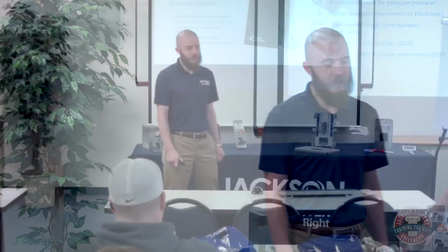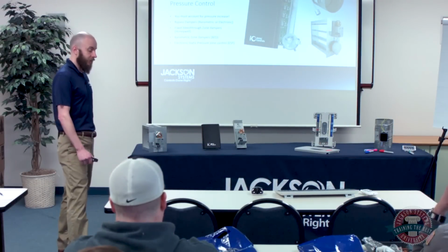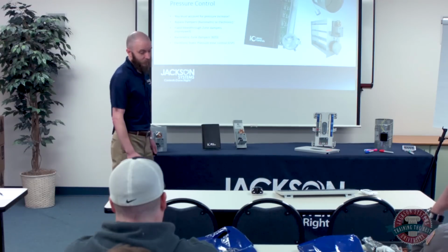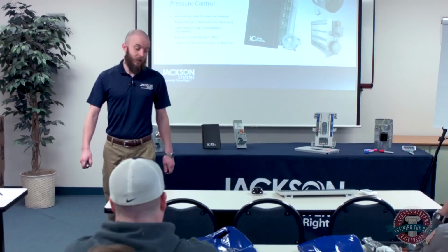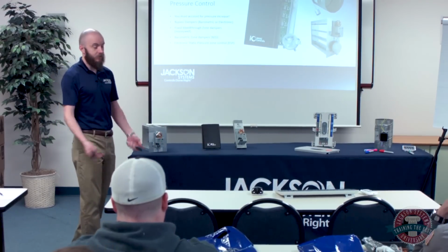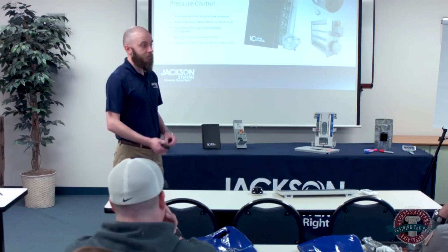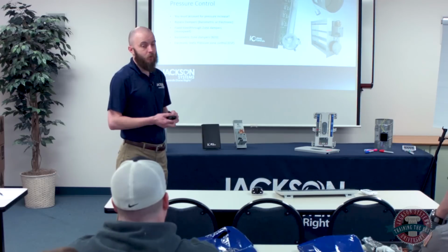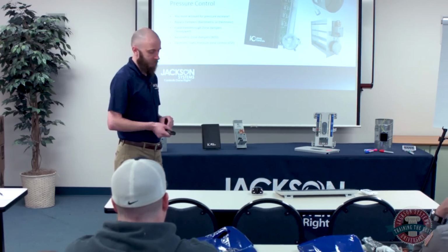We know there's a lot of people out there that install zoning and don't put any kind of static pressure control in at all. We generally don't recommend that. Sometimes you can get away with it. Sometimes you're going to have problems. Even if your increased static pressure doesn't cause any actual harm with the system, if it causes enough noise coming out of the registers, that's going to be a callback, almost guaranteed.